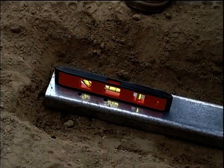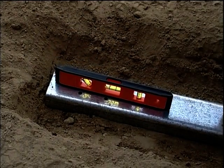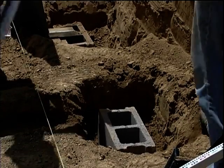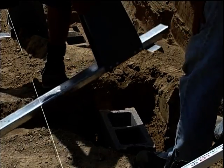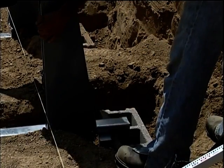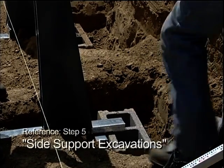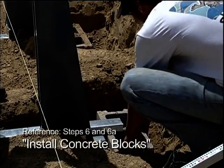Now, check the level of the 36 3/4 inch trench. It should be level with the top of the block. Then place the side vertical subassembly in the trench with the side vertical end on the block, the ground supports in the trench, and the skid plates up against the block. Please reference Side Support Excavations and Install Concrete Blocks.